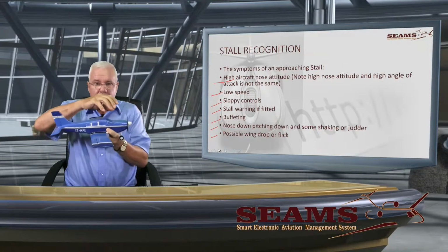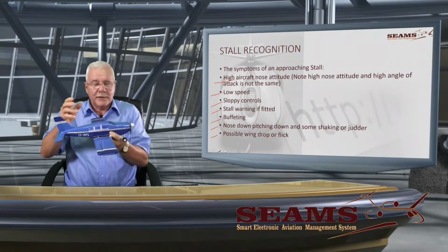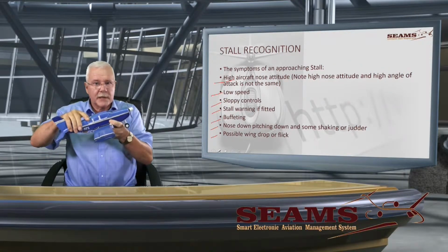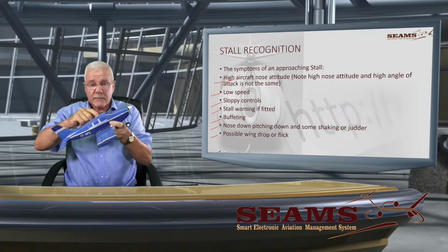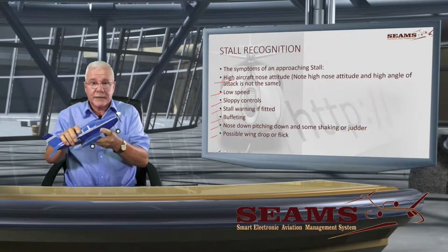So, you've heard it said that attitude is related to speed. That is when the power is a constant. If the power is a constant and you start lifting the nose, you're going to increase the climbing angle and eventually the angle of attack, and the speed is going to come down. All right? So then you look inside and you see the speed is quite low.